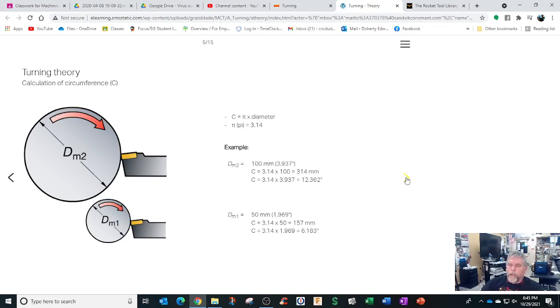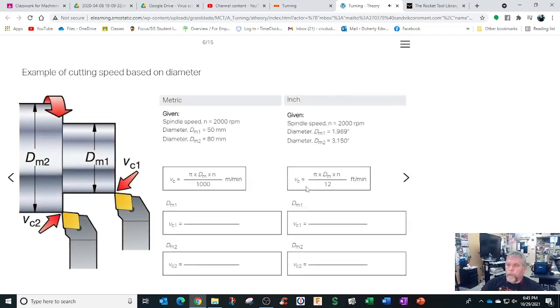So a lathe can run and self-adjust. That's the beauty of a lathe versus a mill. Use the formula to see the difference of cutting. As you start out here, it actually is going to rotate slower. As you get smaller, it should rotate faster. Now, if you have it in plain RPM, like a manual lathe, you cannot do that. Everything's always a compromise on a manual lathe.